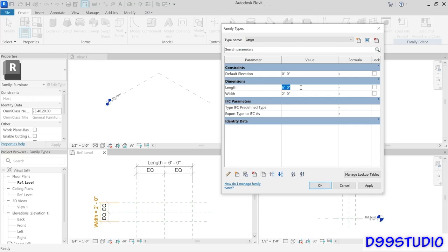But watch this. In Revit, you can put in the unit and it will automatically do the conversion. So what I'm going to do is put in 88 inches. And regardless of which file you're working in, if you're working in imperial, when you enter that, it will format it as feet and inches. If you're working in metric, it will format it as the correct number of millimeters.